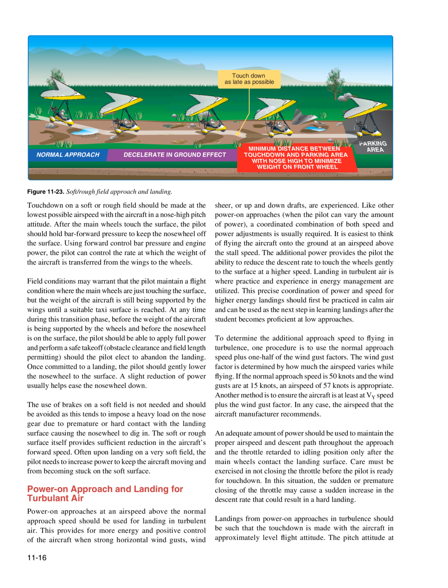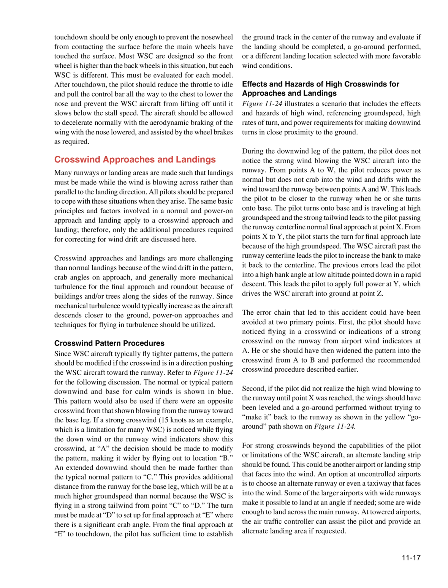Landings from power on approaches in turbulence should be such that the touchdown is made with the aircraft in approximately level flight attitude. The pitch attitude at touchdown should be only enough to prevent the nose wheel from contacting the surface before the main wheels have touched the surface.